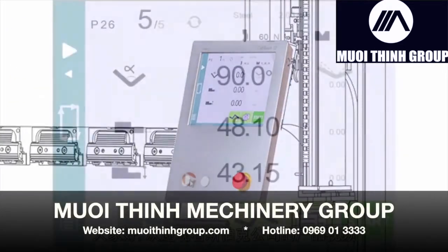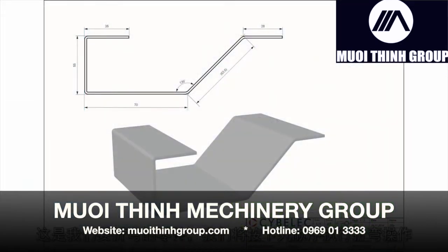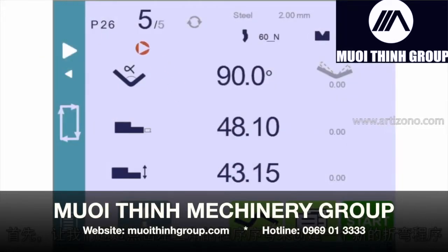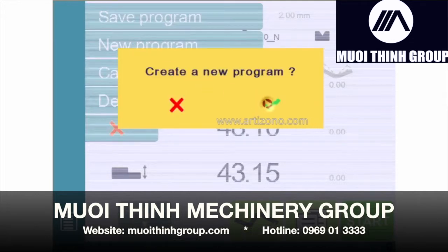Hello, and welcome to this Symbolic video, where we'll show you how to program a part in numerical mode on our SIB-Touch numerical controls. This is the part we want to bend, and we're going to execute the bends in the following order. First, let's create a new program by touching the program number in the top left-hand corner.